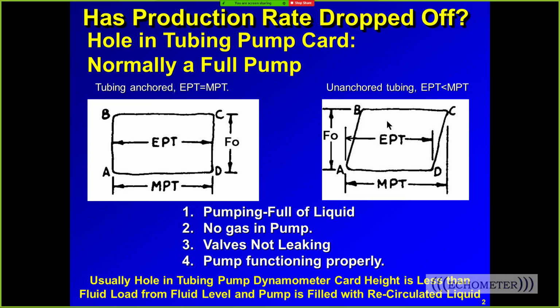And in effect, you're not drawing the well down. A well becomes typically static because there's no production from the reservoir. When there's a hole and no production is being produced, then the well becomes static. There's no annular gas flow. Often, if you shoot a fluid level on a well that has a hole in the tubing for a period of time and you measure the casing pressure buildup, there's no casing pressure buildup because there's no flow.